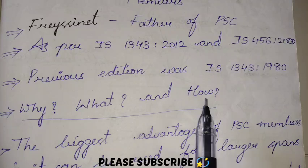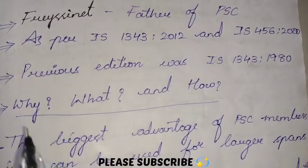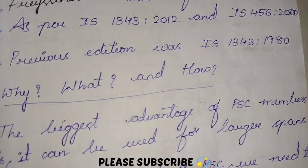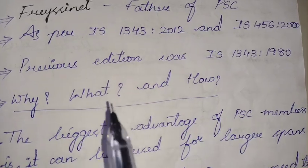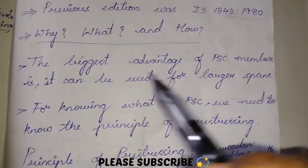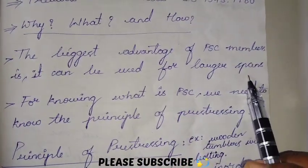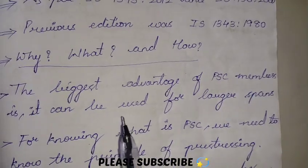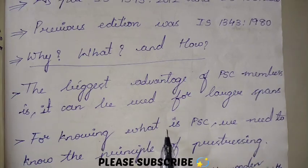So why, what and how we can go with prestressed concrete members, why we are choosing this over the conventional method of concrete structures, and what the advantages of using this are, we'll be seeing now. The biggest advantage of PSC members is that they can be used for larger spans. We can see that prestressed concrete is ideally suited for long span bridge construction.